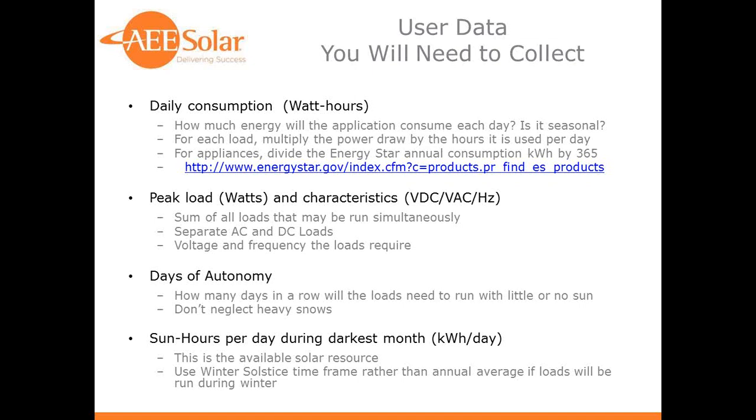So we need to know what those loads are, and we need to account for those quite well. You want to look at each load, typically make a list, and I'll go through that in a little bit here. You multiply the power draw of the load by the number of hours it's used each day to figure out how much energy it's going to consume on a daily basis.